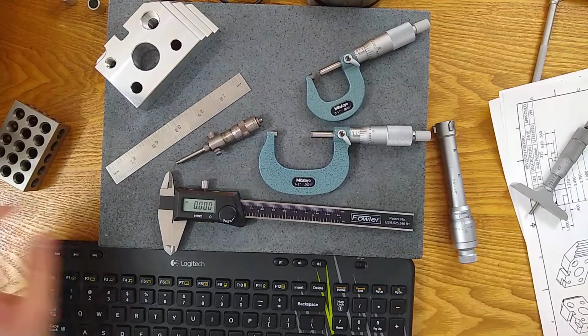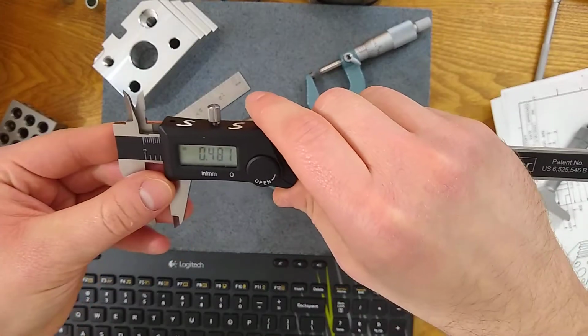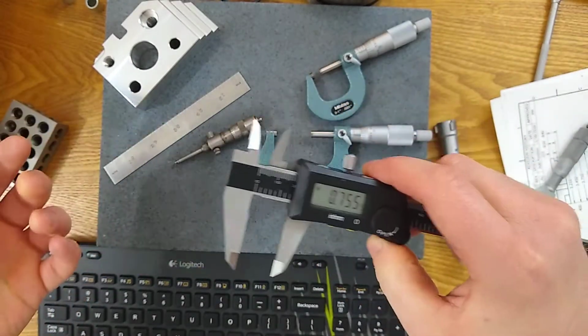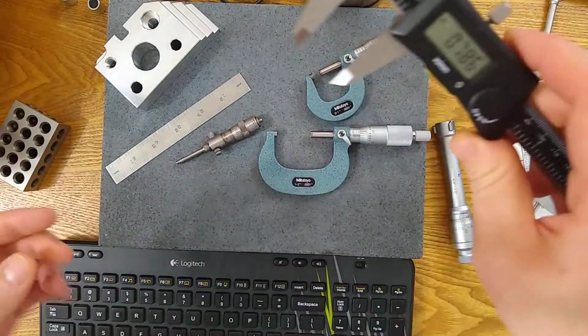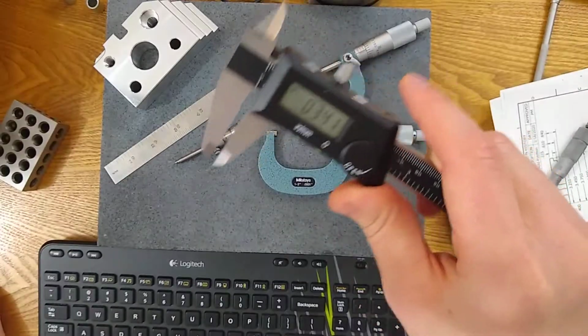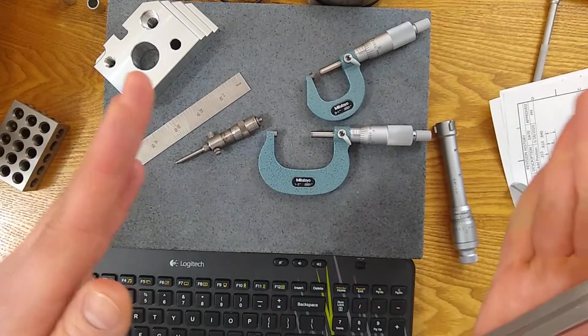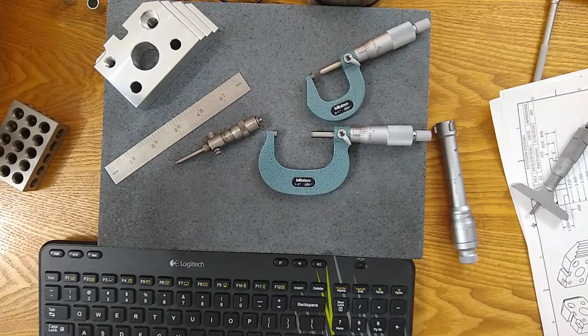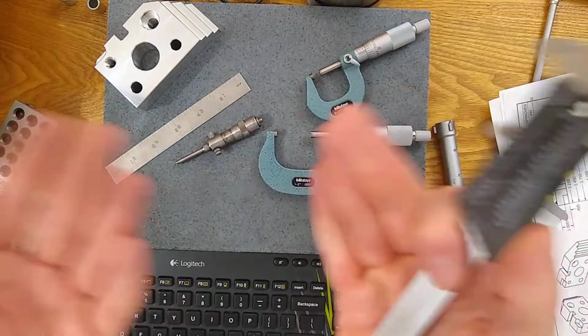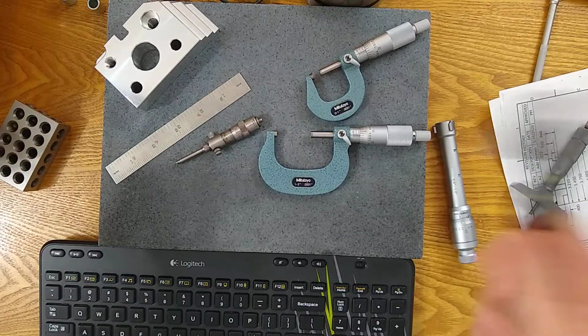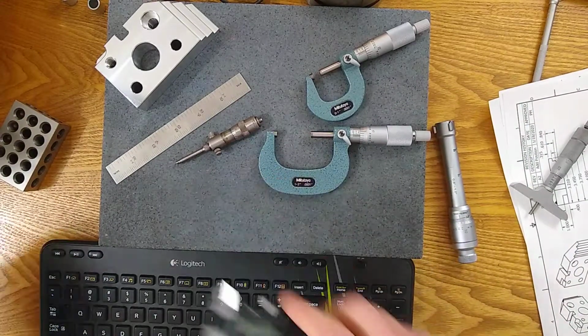We talked about before, pretty much you need 10 thousandths at a minimum to use a caliper, and we've got 30. And we have our accuracy of plus or minus 2 thousandths. So again, plus or minus 2 compared to 30, as long as we're relatively near the middle, we've got no issues. So we do our caliper measurement, right?